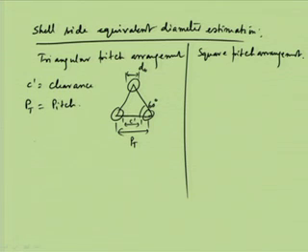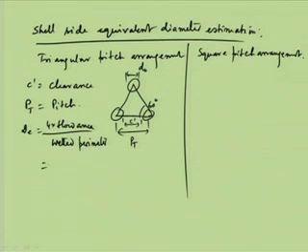Under that situation, we know that the equivalent diameter is 4 times the hydraulic radius, and the hydraulic radius is the flow area by wetted perimeter. So, DE is equal to 4 into flow area by wetted perimeter, and this happens to be 4 into half into base into height, and the height is √3 by 2 into base. So, we can write half into PT into √3 by 2 PT, which we have already discussed, and minus half of the area of a tube.